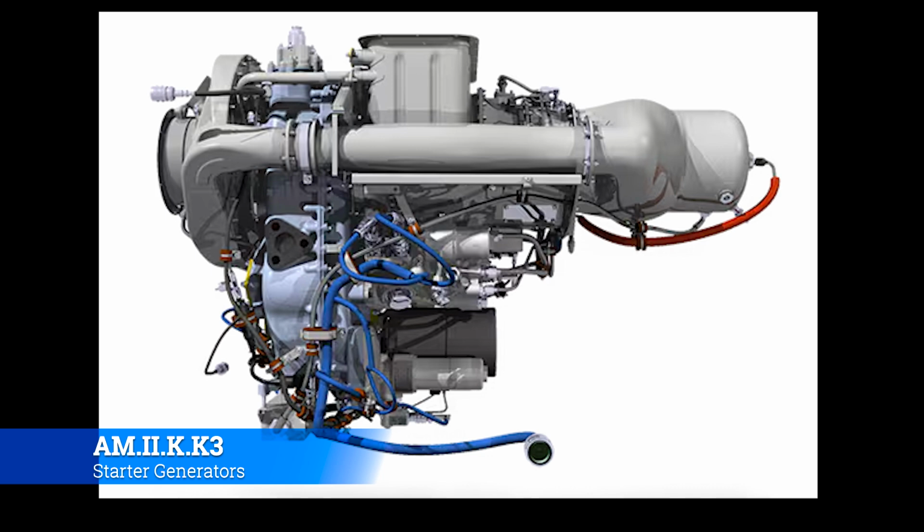And that's where it sits on the Allison slash Rolls-Royce turbine engine. If you look in the center of the engine, at the very bottom, there's a big gray square looking thing that actually is the starter generator, and it just mounts right up to the accessory gearbox of the engine, which you'll understand more when we get into turbine engines. But notice that it just plugs right up, and it's always connected. It's always turning. The real question is how is the electricity flowing through it? Is it being generated and flowing out of it, or are we taking a battery and charging it so that it'll action and start the engine?